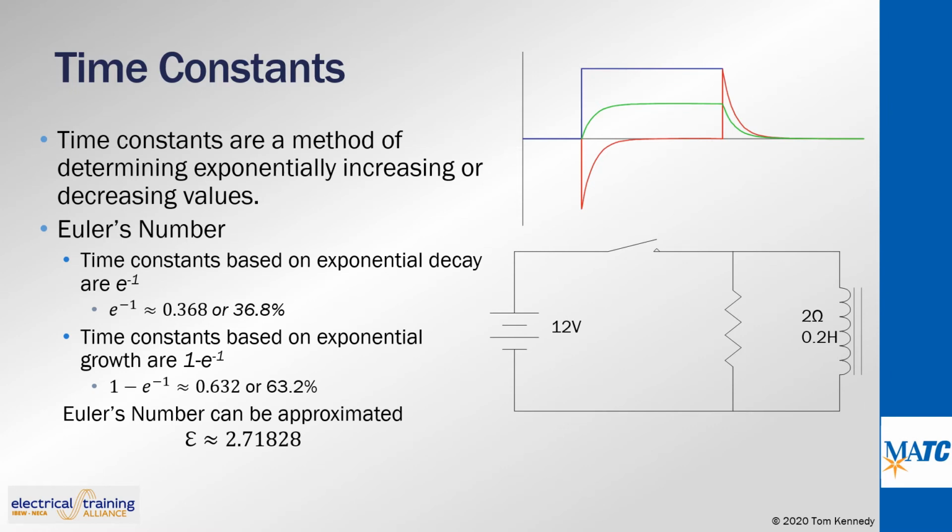The magnetic field expanding and contracting around a conductor is based on the inverse square law. Therefore, the value of increasing current or decaying CEMF is an exponential rate of change. The interaction of these magnetic fields is given by the value of inductance in henries. The CEMF created by a coil when a DC voltage is applied will decay at an exponential rate as the magnetic field expands and slows to a stop.